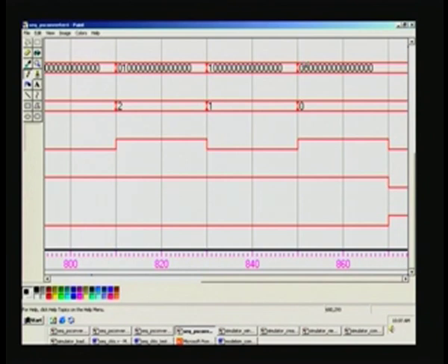So, the very last must be 1, because it is a left shift in 0 1 0 1 0 1, right. So, the last bit will be 1. So, after 16 shifts here, and once again data valid goes low and end of conversion is activated here, and this completes the parallel to serial converter, and we will go on to